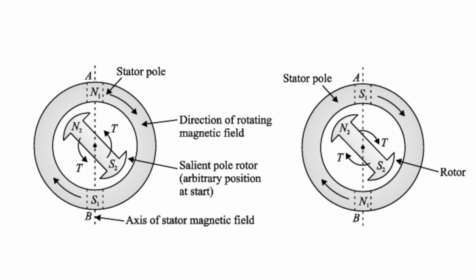speed. The synchronous speed of a stator rotating field depends upon the supply frequency and the number of poles for which the stator winding is wound. If the frequency of AC supply is F Hertz and the stator is wound for P poles, then the speed of the rotating magnetic field, the synchronous speed, is given by Ns = 120F/P. In this case, say the stator is wound for 2 poles with a 50 Hertz supply. The speed of the rotating field would be 3000 RPM. This effect is similar to the physical rotation of 2 poles with a speed of Ns RPM.